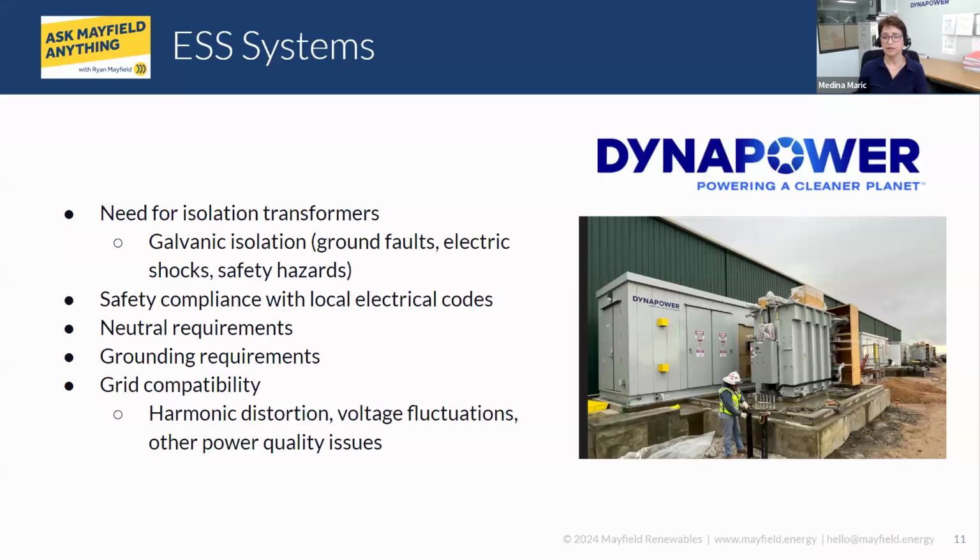For example, if they had a 480 volt rectification system and now they have 240, we would provide an autotransformer because it's much smaller size-wise and still provides everything that's needed. The equipment still keeps its own main transformer. The autotransformer just provides that different voltage level, in which case isolation is not really needed.